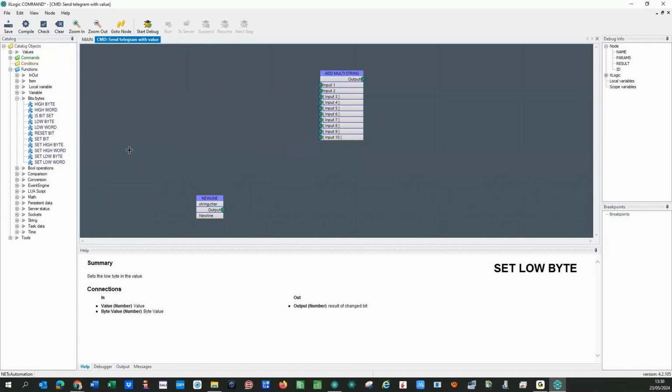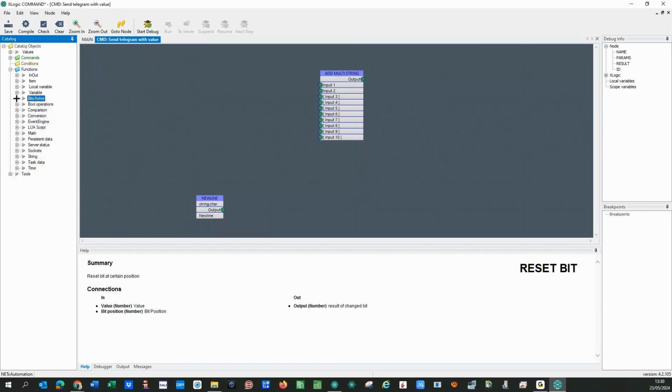So when you are also working with Modbus, it's interesting to have these possibilities. So you can set or reset a bit. So set is put in 1, reset is put in 0. All these operations are possible also. So I'm just showing a lot of possibilities. About variables, if a variable exists or not, the name of the variable, the value, it's also possible. This is global variables, the same with local variables. It's possible to manage this.